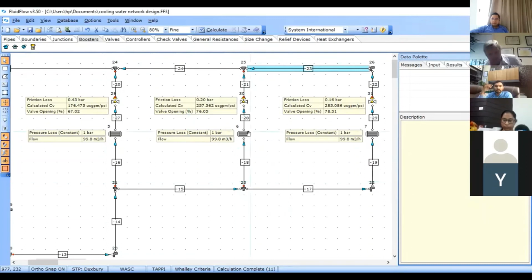All right. So let us proceed. One more doubt. Yes, sir. What if we have the control valve or the restriction orifice before the exchanger? It will work fine. Typically, it will be on the downstream of the exchanger. The reason being, if I keep it on the upstream, then there is a chance that I'll starve this exchanger for the water or whatever fluid it is.